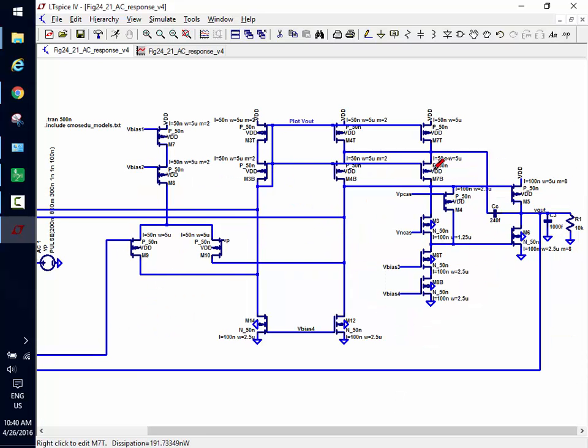If I've got this structure here, and I've got this structure here, which I could basically put in the middle here, why do I need this branch? Why don't I take these two devices, put it over here, and just move everything and just get rid of these two? Does everybody see that? It's wasteful. I don't really need these two transistors and these two. I needed them before because I didn't have the ones on the bottom. Now I don't need it. I can take these two and put them over here, take these and put them over adjacent, and simplify the circuitry. Okay?